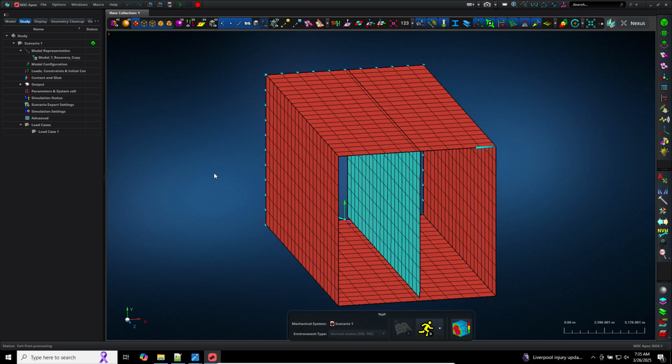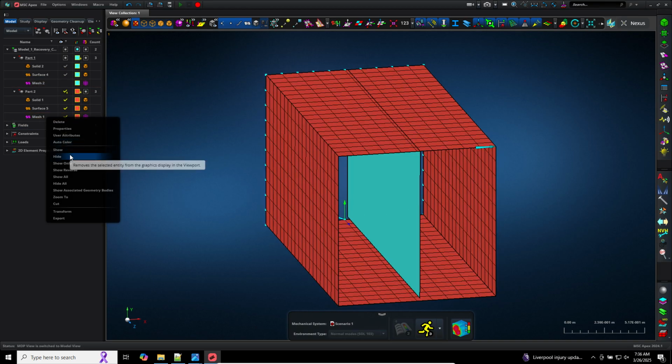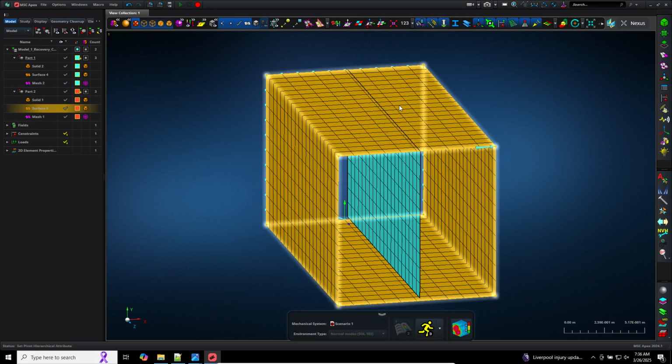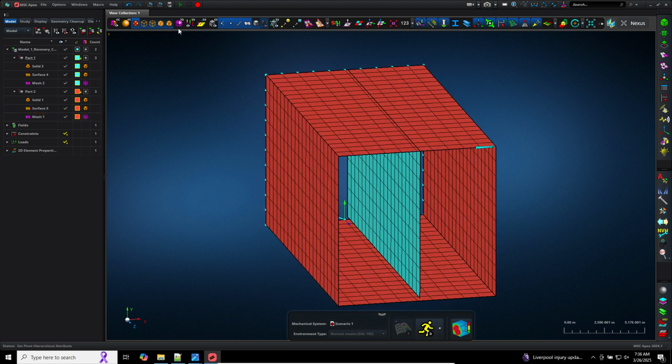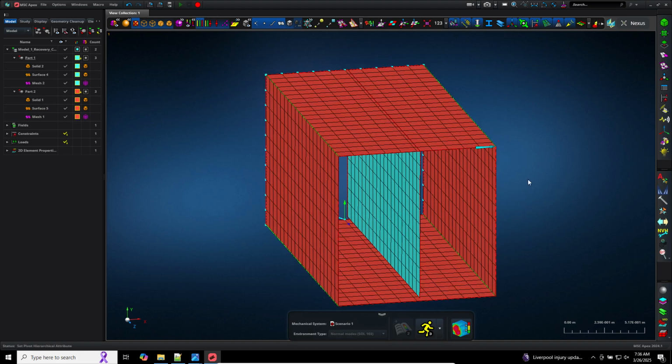So now let's go ahead and go back to Apex. Let's go ahead and maybe hide the mesh. So let's right click these meshes and hide them. Now, let me take a step back and look at the mesh. When you look at the mesh, it looks like everything is fully attached. But here in the vertical bar tools at the top, there's this button, Geometry Visualization. You can click on this option, Topology Lines of Visibility. This will show you the green, the yellow, and the red colors for the edges.